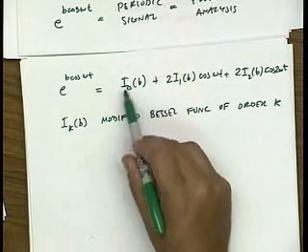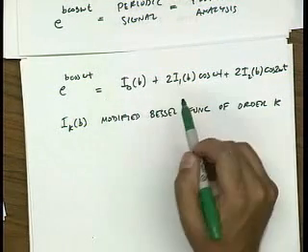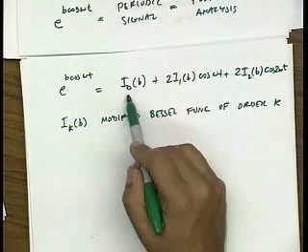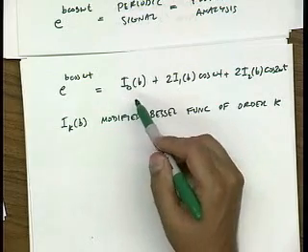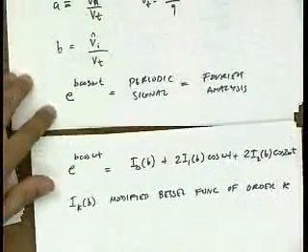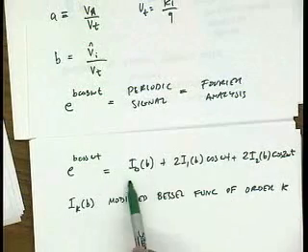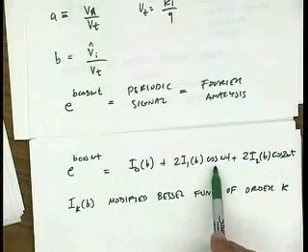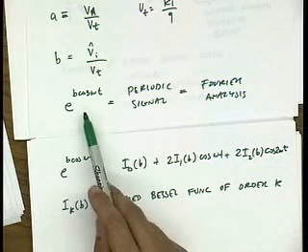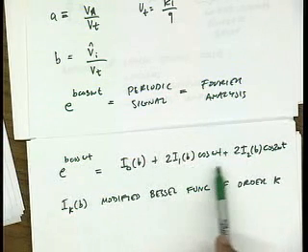These functions are more like exponentials. It's like the analogy between hyperbolic functions and sinusoidal functions. The J's are like the sinusoidal functions, and the I's are more like the hyperbolic functions. So no magic here. All I've done is ask what the Fourier series for this is. The Fourier series has a DC term, a cosine omega t term, a cosine at 2 omega t, and so on. Because of the even symmetry, it's a cosine series with no sine terms, and the coefficients are just these modified Bessel functions.